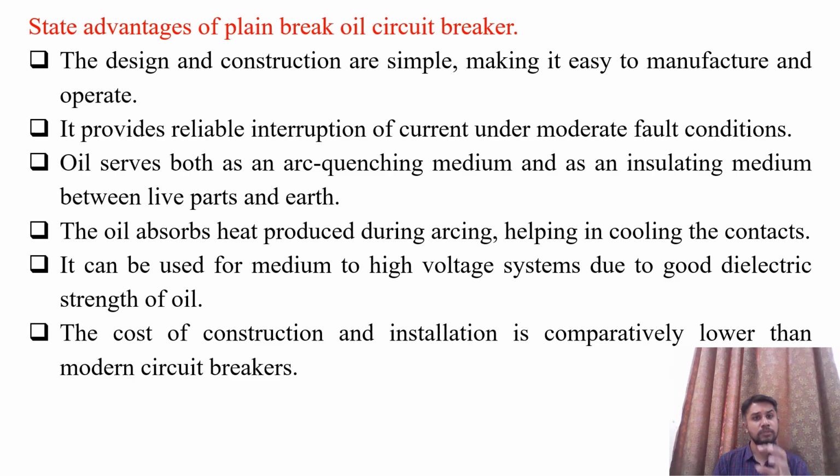The oil absorbs heat produced during the arcing, helping in cooling the contacts. It can be used for medium to high voltage systems due to the good dielectric strength of the oil. The cost of construction and installation is comparatively lower than the modern circuit breaker. So these are some advantages of plain break oil circuit breaker.